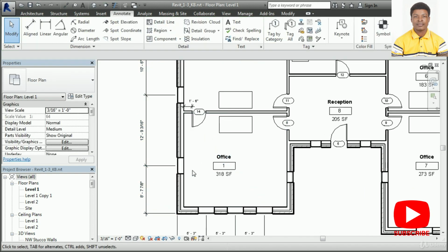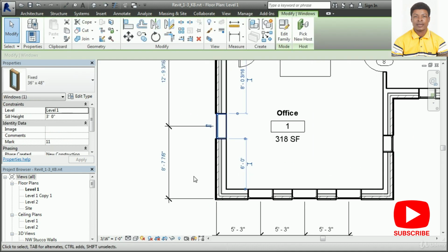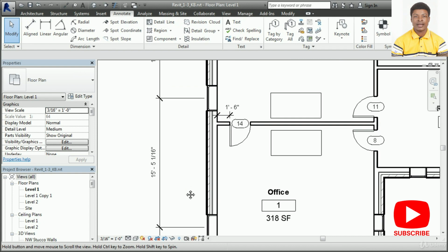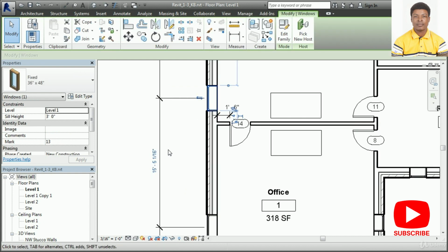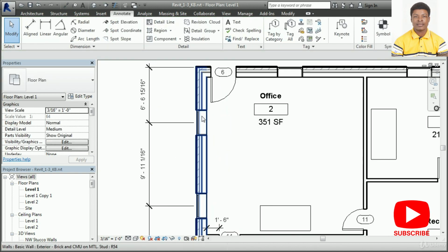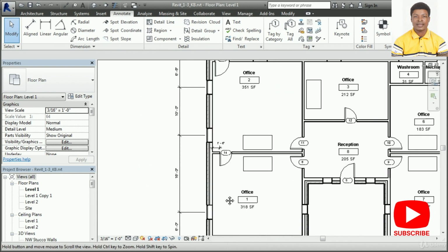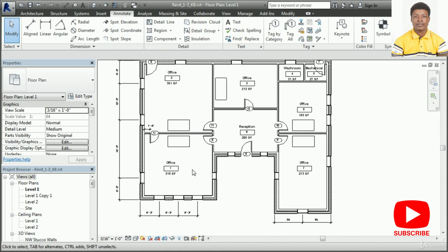And if I want to change these values from one side to the other, I'm going to pick the object that I want to change, set a distance. So I'll say that that will be 6 feet to the center. And then I'll just move my way up, and I'll say that this next window is going to be 16 feet from the first. And the first one didn't change. And then I go to the next window up, and I'll say that I want this to be 10. And enter. And that's how you can modify your string of dimensions. So you start at one end and then work your way along.